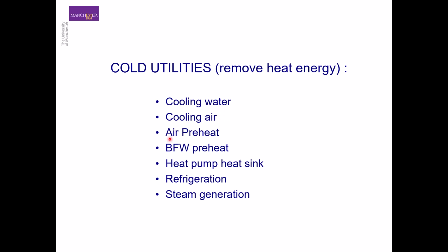We can use air preheat and boiler feed water as cold utilities. Then we can use heat pump and refrigeration. So refrigeration is used mostly when you have temperatures way below ambient. And obviously we try to avoid refrigeration because it is very expensive.